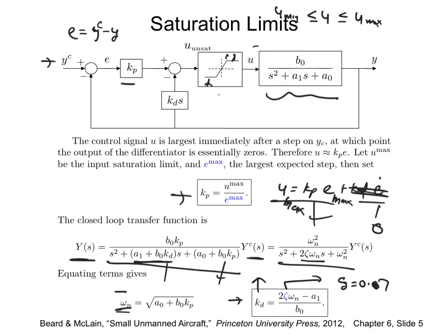And I think everybody's mass spring damper system is going to 1? It should not, because there is a DC gain, so it does not go exactly equal to 1. You have to either multiply your input with that DC gain. Otherwise, mine was kind of reaching 0.6 or something.